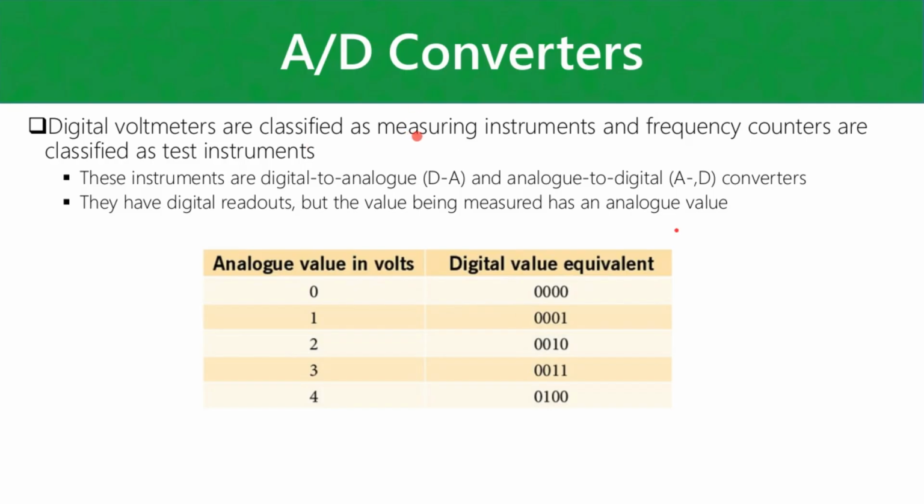Okay, so we're going to take a look at analog and digital converters. Essentially, we take an analog value. Usually your analog values are an analog voltage, for instance, or analog current. It's continuously changing, whereas with digital, your changes are in discrete little steps. It's usually associated with a binary value as well.